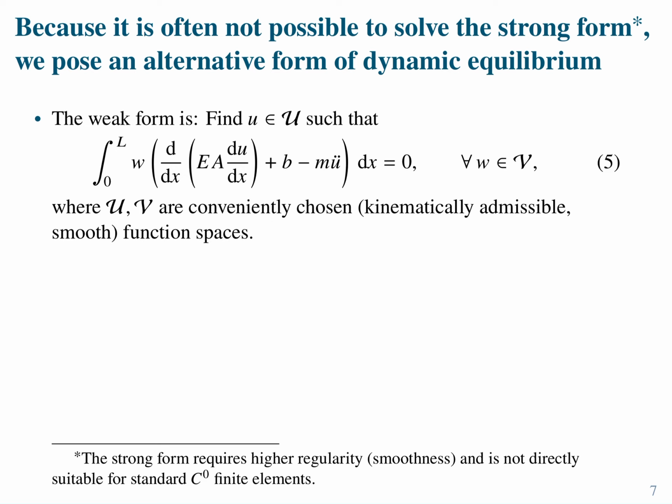We saw that we have a requirement on a second derivative of the field in our differential equation. So we can no longer use linear shape functions in our elements. And so by casting the strong form in a different way, as we will go through in a minute, this is a variational form, we are able to lower the differentiability requirement on what we are going to be calling the trial solution, right?